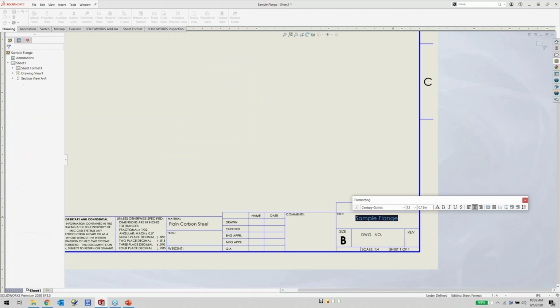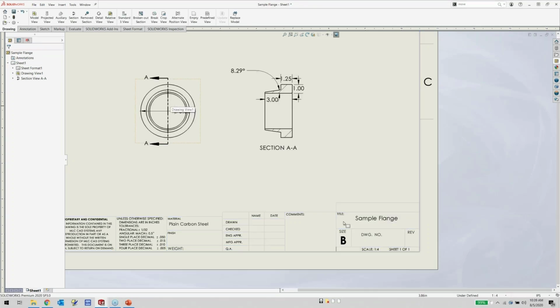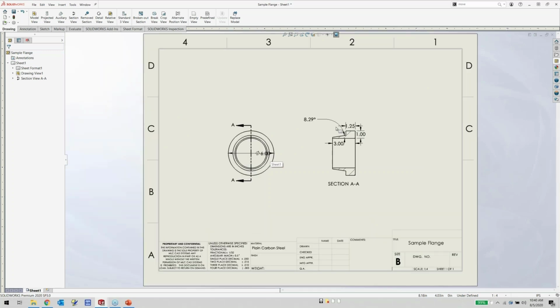Now, this offers a few opportunities depending on what we choose, but in the sheet properties, there's the basis view, and it's usually the first one that goes in, and I can pull the description directly from there instead. Now when I save this template, it will use the first view that's placed on the drawing and pull that description in. Same thing can be done for drawing signatures and dates. We can pull any of the information, drawing numbers and revisions and everything like that. So those are all possibilities and all available to us. So starting from scratch, getting all the way to something that is very efficient for us to start to use just takes a few minutes and adjustments in order to save it back so that we can use that.